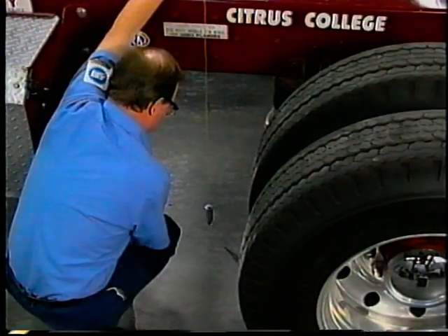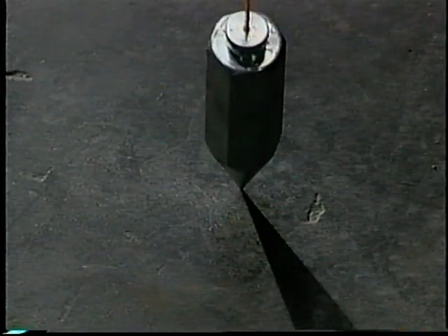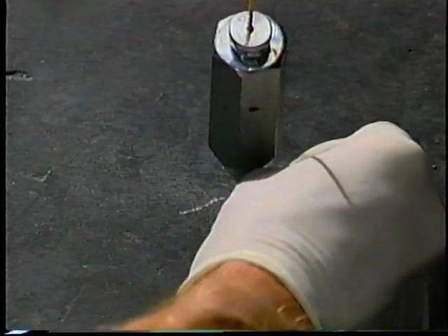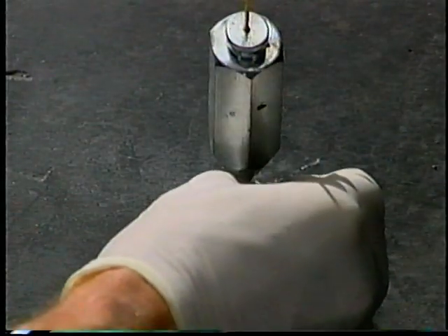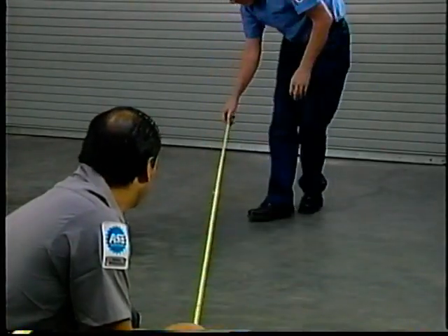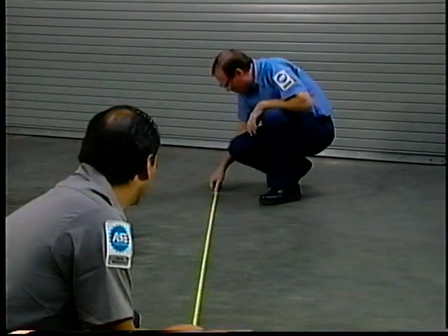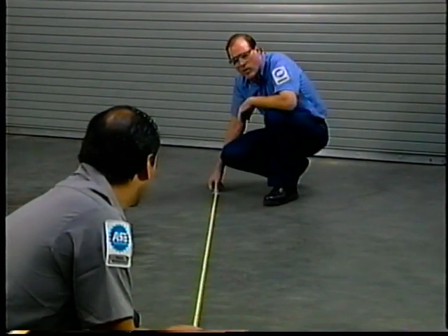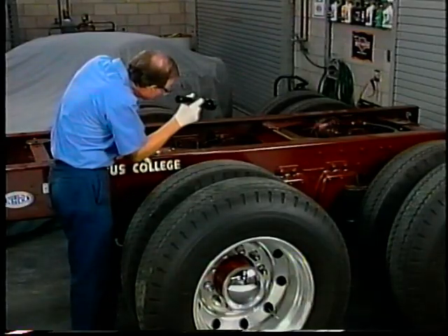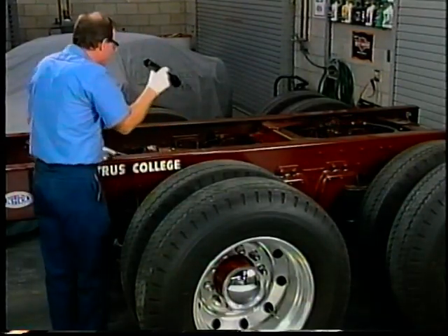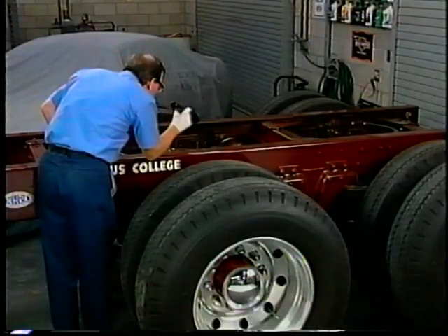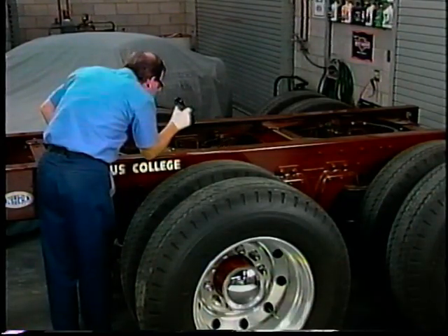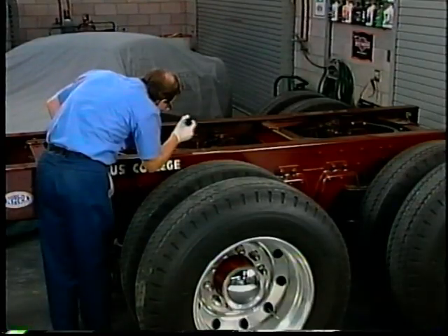Diagnosing frame misalignment is usually done with a plumb bob to mark location points on the floor. With the truck removed, the distance between the location marks on the floor can be measured easily and compared to the vehicle specifications. If the frame requires repair, the frame can be straightened or reinforced with fish plates, C or L channels. Straightening requires the use of a frame press.